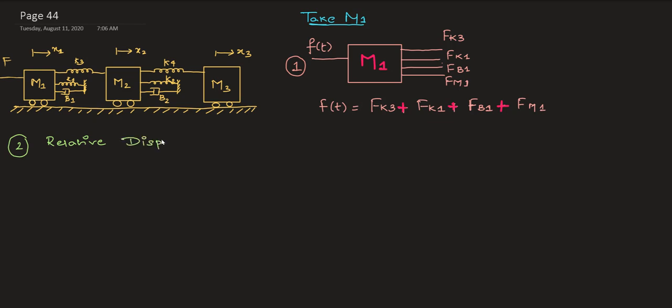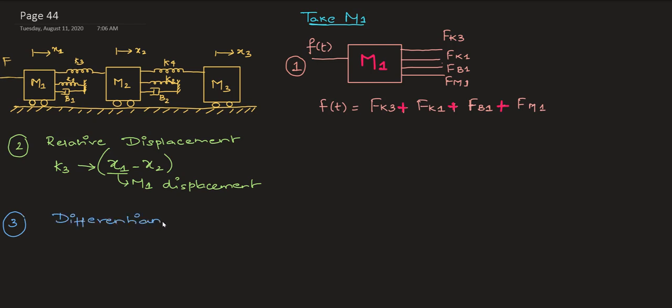In the previous lecture, we took the differential representation and converted it into Laplace representation, which helped us in obtaining the transfer function. In this case, we are going to use the differential representation to derive the electrical representation, the voltage representation in the first case and the current representation in the second case.